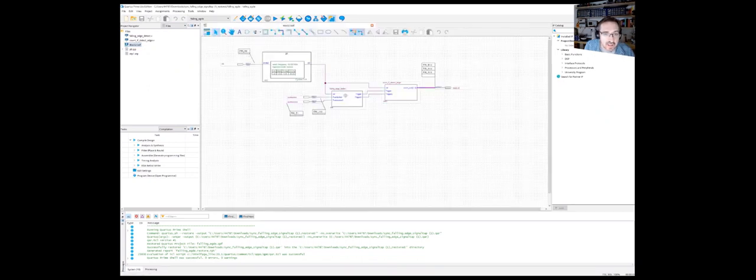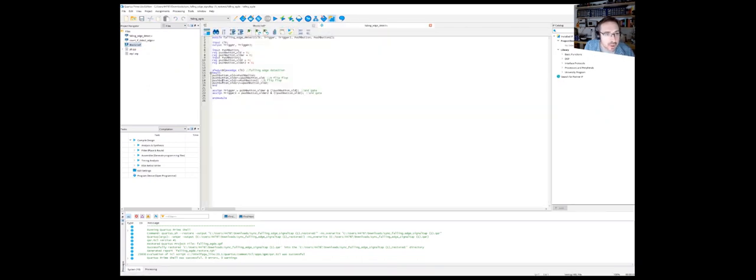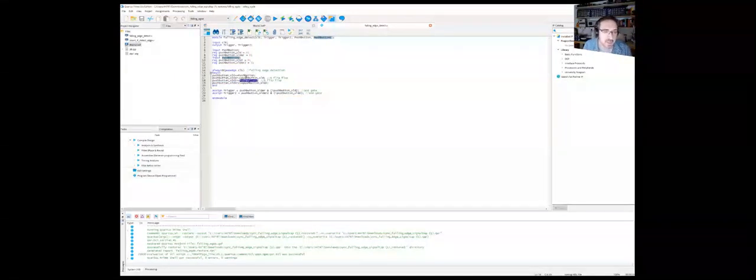Very similar design, except this time we have those two synchronizer stages. It's just non-blocking assignments, which in hardware are D-type flip-flops. So you can have a look at this code and satisfy yourself that this is two D-type flip-flops. And as I said before, it's duplicated because we've got two push buttons, so everything happens twice.